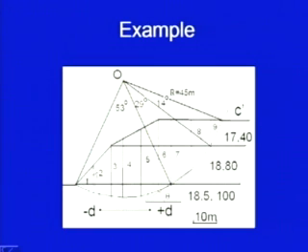So simply, you have to find this area. Let us say area A1, area A2, then A1 into 1 into its unit weight plus A2 into 1 into this unit weight. That will give you the weight of this slice.